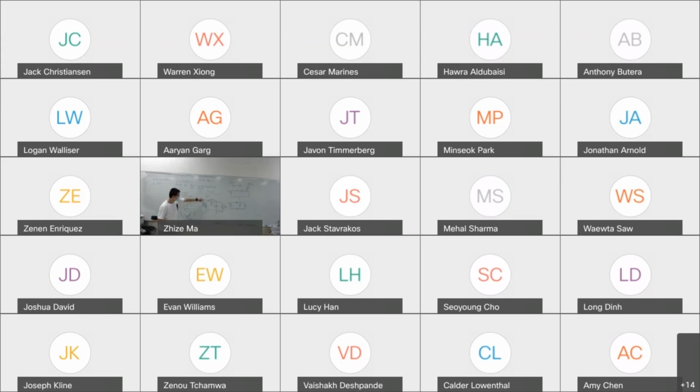So W1 to amp, and the amp goes to the common, and the common goes to the resistor. And the resistor goes to one side, and another side of the resistor goes to the ground. The ground pin will be either one of them from your AD2. And then you will use AD2 to measure the voltage across this resistor.